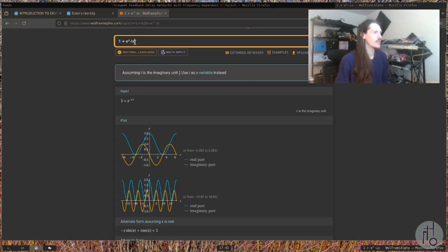So when you're looking at a frequency response like this, 2 pi is like the sampling rate, and this middle here is the half Nyquist rate. This is the maximum frequency that you can actually represent. So the part of the graph that we care about is just this bit that goes from 0 up to pi.